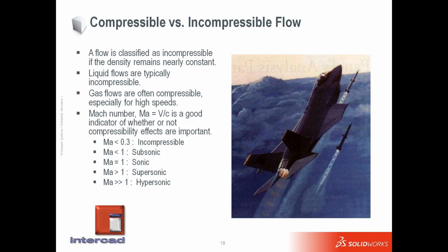Next classification is compressible versus incompressible flow. A flow is classified as incompressible if density remains nearly constant. So it depends on the pressure you apply. If the density is not changing, it is incompressible flow. Liquids are typically incompressible, but in contrast, we have gaseous flow, which is mostly compressible,